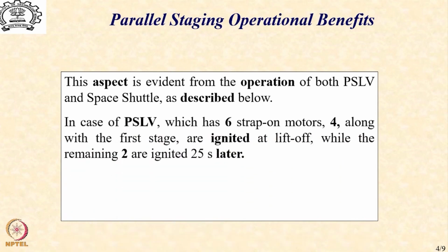So in the case of PSLV, the normal configuration with boosters contains 6 strap-on motors of which at the liftoff only 4 are ignited along with the first stage.